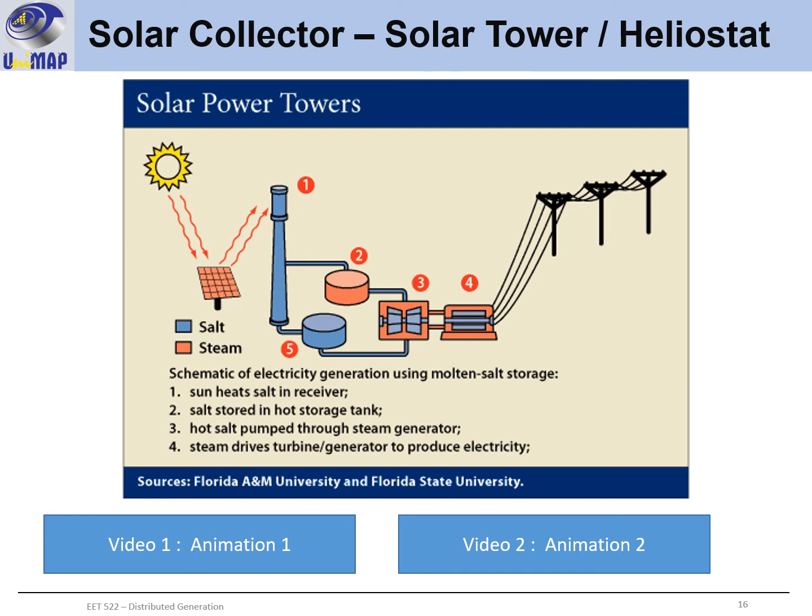Okay, this slide shows how the solar tower concept works. When the sunlight is received here, it will be reflected by the thousands of mirrors around the power tower. So by having that, we will concentrate all of the sunlight to the receiver here. In the receiver, there will be some tubes or pipes that contain the molten salt. The material used is the molten salt due to the high heat containment characteristic of the molten salt.